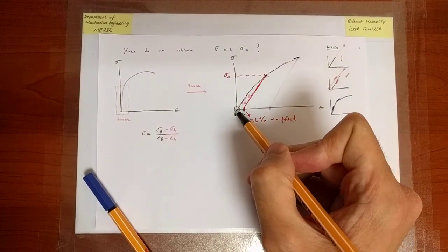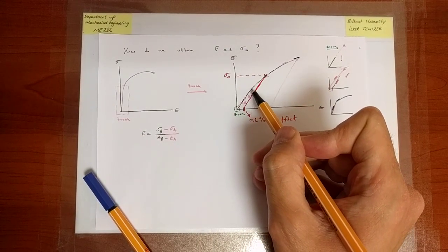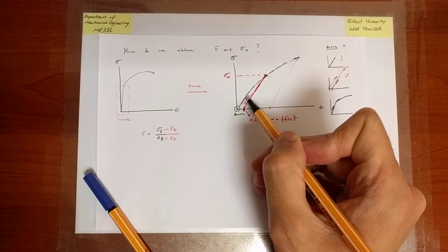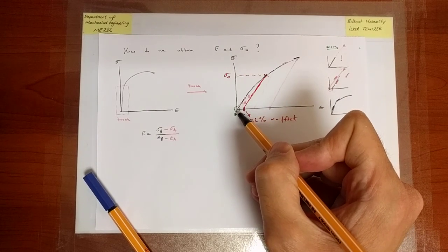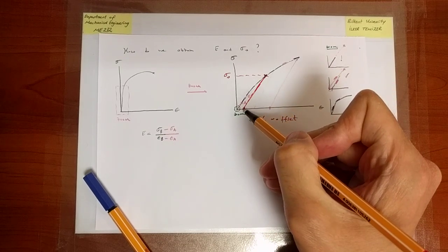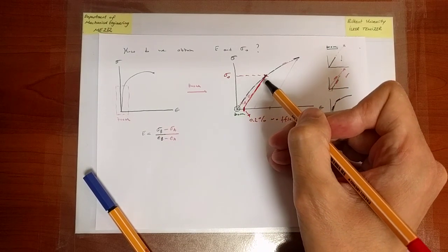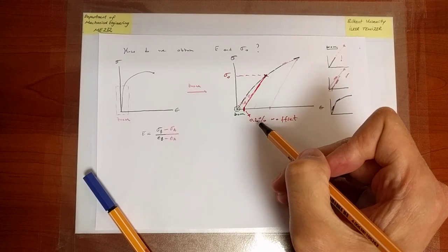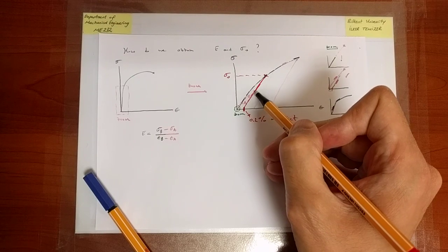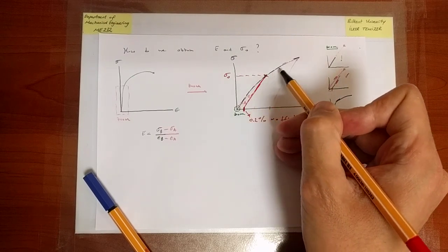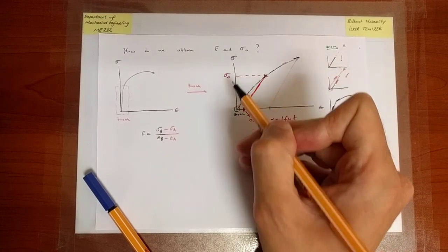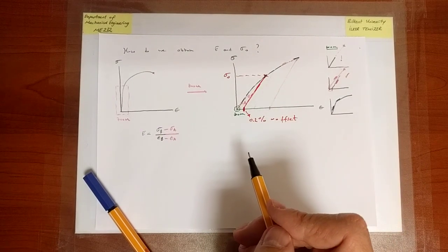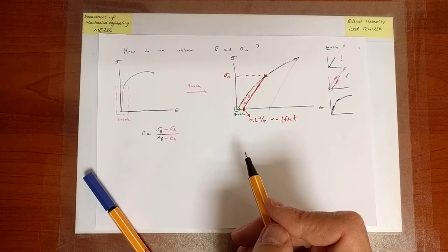Okay, so you start the curve, you follow it, and once you identify the Young's modulus, then you start drawing a line that is parallel to it, such that that line intersects the strain axis at 0.2%, and where that red line intersects the real stress strain curve is going to be indicated as the real, or the experimental, yield strength of the material.